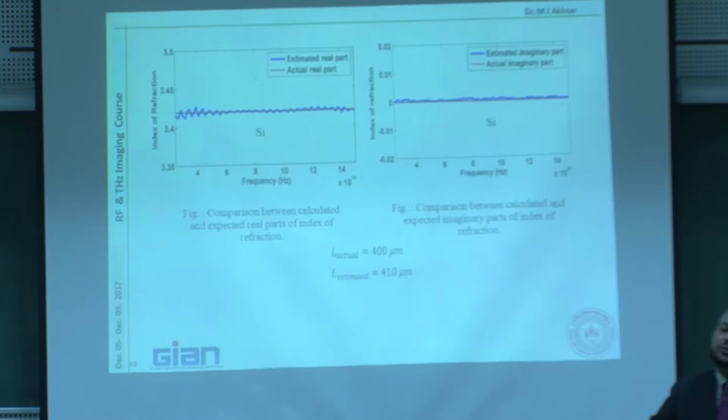in order to check your algorithm, because there are two independent things. One is your standard simulator, the other is your handwritten program. This is the direct program, which gives you S-parameter data, and here you use this data in order to extract the material property or the object image. So that is a very good way to check whether what you are doing is correct or not,